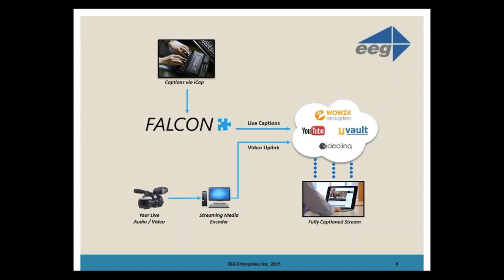Now, that's one of your options for getting audio delivery. It's not your only option. Also, for example, clearly the captioner could watch the consumer stream for the audio, especially if it's not heavily delayed. You can also use something like a telephone coupler or an IP audio sender, something like one of those Barix converters is pretty commonly used. So you have some options in terms of how the audio is going to be delivered depending on what equipment is available on site at the event, and what's giving the captioner acceptable quality for a given situation.